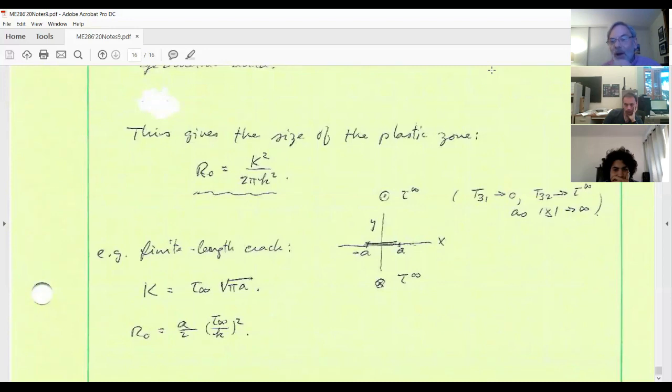And in fact, if you have hardening of the material, here we had elasticity with a definite modulus and then perfect plasticity. If there's hardening after yield, then it turns out that's a substantially more difficult problem, even in the anti-plane case. You'll still have a circular boundary between the elastic and plastic regions, but the plastic zone will engulf the crack tip.